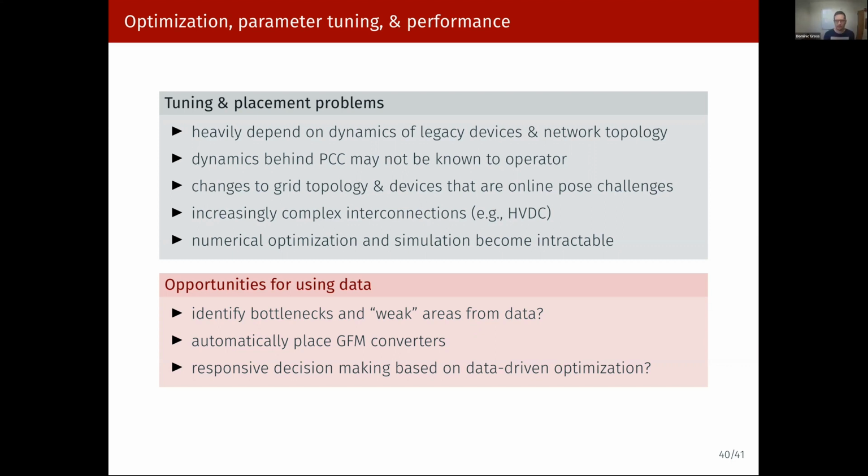The other one would be, sorry, let me rephrase this. You can either have a lot of lines, but they could be relatively high impedance, and then it doesn't matter. Or you can have one line with a very low impedance, very high admittance, and then that would also be strongly coupled. So I think it's both in terms of how many lines do you have between different parts of the system, and how big is their impedance. At least that's the way we're using it here.